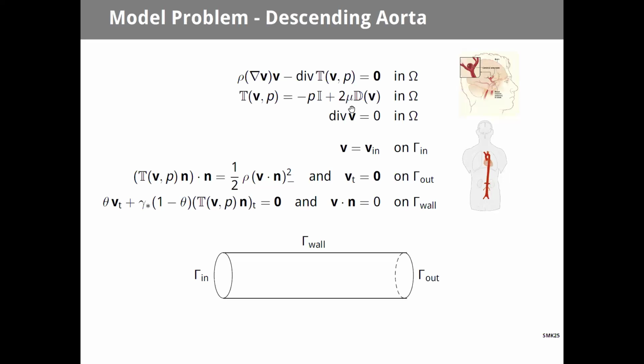So for the blood, usually apart from the incompressibility, you can make some more complete, more sophisticated model for the viscosity, like shear thinning, that depends on the location. So in the aorta, constant viscosity is a perfectly good, accepted model. In the smaller vessels, you would consider some non-Newtonian viscosity.